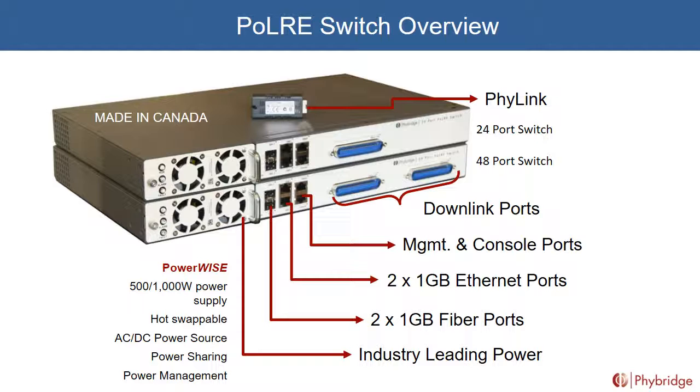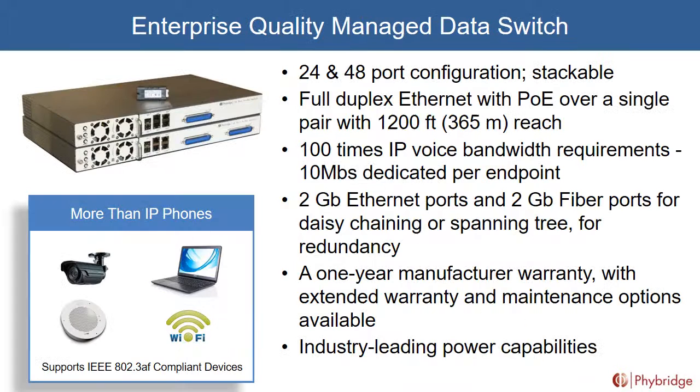Let's talk about managing this now. Absolutely. This is an industry-leading management capability. They're fully stackable. We've got customers with hundreds of these switches connected together. It's full duplex Ethernet with PoE and a single pair, as you can see. It has a 10 megabit per endpoint on the downlink side, which is 100 times more than your IP phone needs. An IP phone typically needs about 100K of bandwidth. It does have the uplink ports. You can connect them together for redundancy. We provide the manufacturer's 1-year warranty.